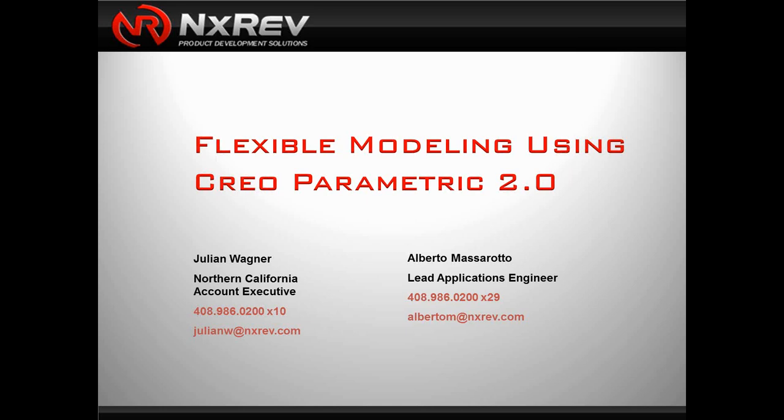The question is about the flexible modeling tab being missing after installing flexible modeling. During the installation process, there is actually an option to turn it on in Creo Parametric. So we can definitely take this offline and help you out. Just go ahead and shoot Julian an email or myself, and we'll definitely help you out. Yeah, so the question was basically flexible modeling was installed, but it is not showing up in the ribbon. There is a configuration to turn on for that.